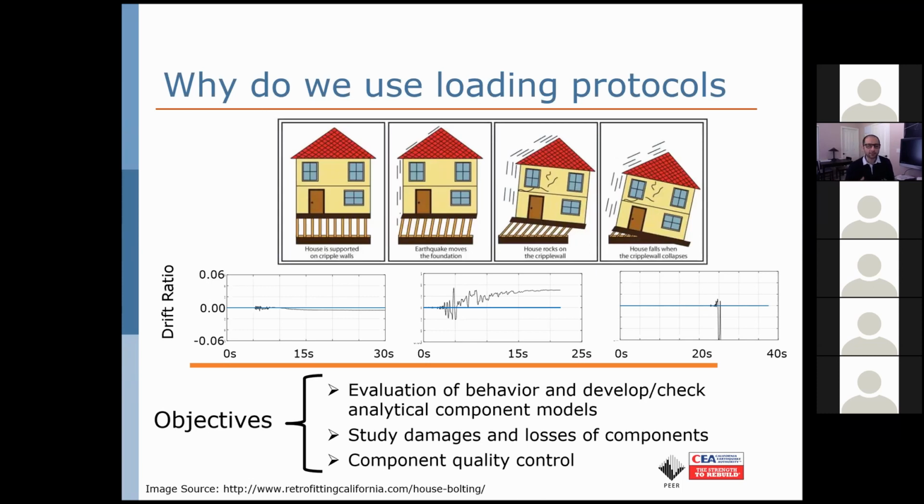Now, with this image, what I want to do is start the conversation and say, why do we use loading protocols? There are three objectives. One is that you might want to do an evaluation of the behavior of your components, in this case, cripple walls, and check your analytical component models. This is what we actually did in this project. That was the intention of developing these loading protocols.